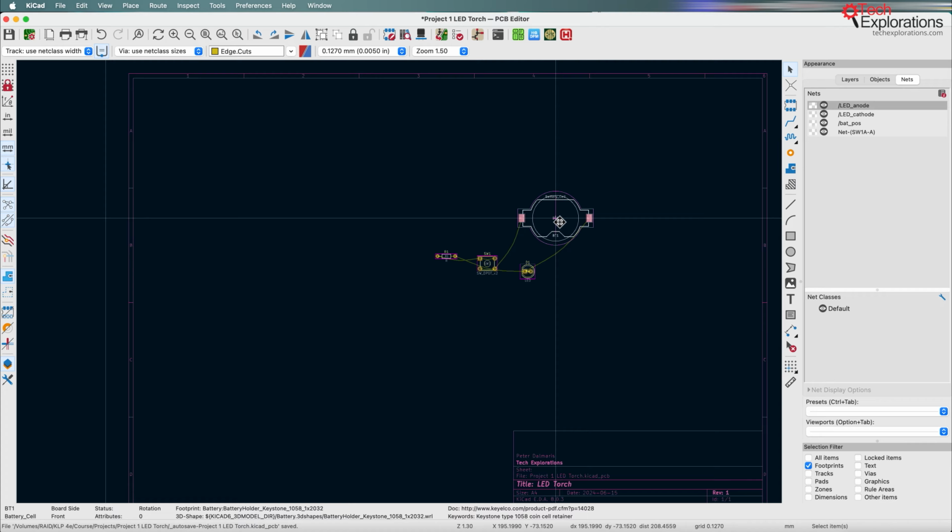For example, I want to have the option of designing a simple 3D printed enclosure, and then I have to figure out how to mount the PCB securely inside that enclosure. It could perhaps be done with clips or with a mounting hole. I can use a screw to secure it against the enclosure. That's another consideration. So these questions will help me determine the physical dimensions and the shape of the board.